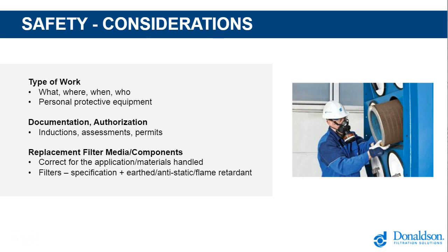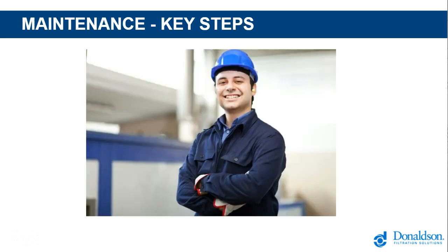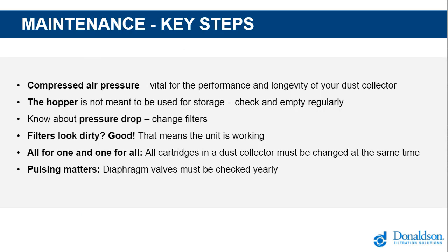So here, some of the key steps, some important points before we go into some of this servicing detail. Compressed air pressure, and Bart was talking about that a little bit earlier. For a reverse jet filter, this is really vital to the performance of the equipment and the longevity of the equipment as well. It's not only just the compressed air pressure itself, it's the quality of that compressed air, and also making sure that you have the correct air volume.